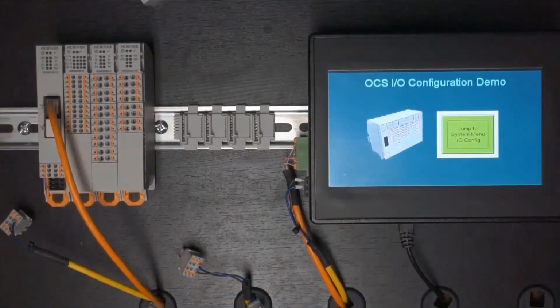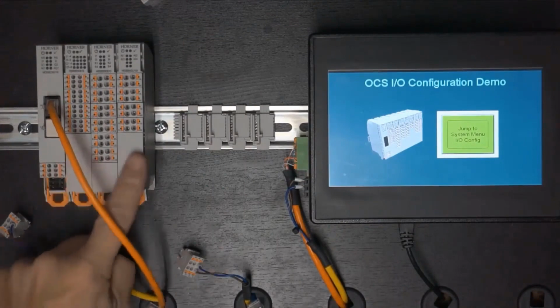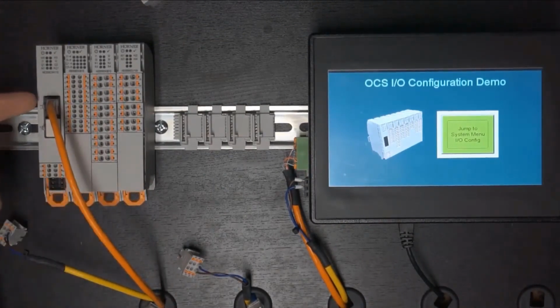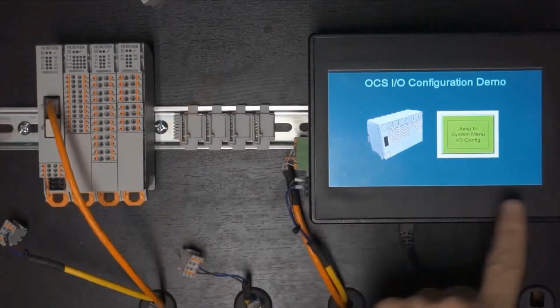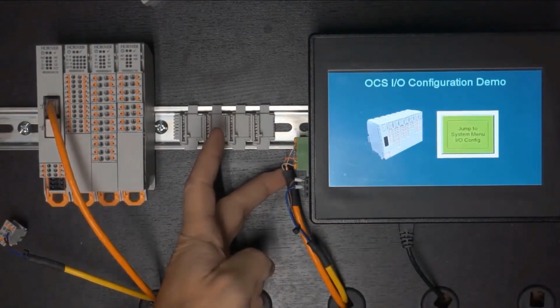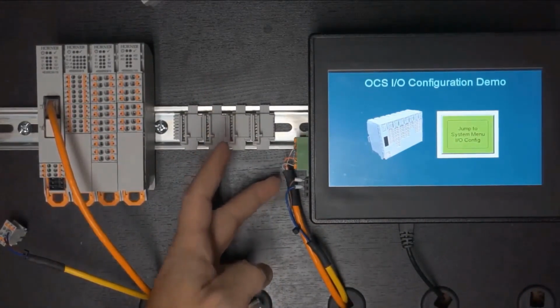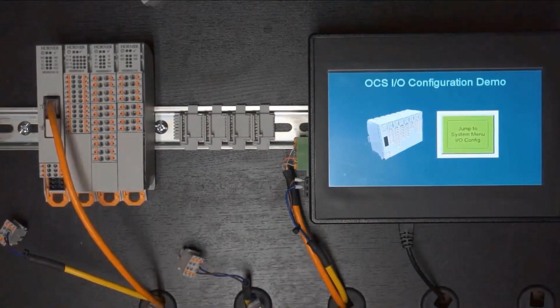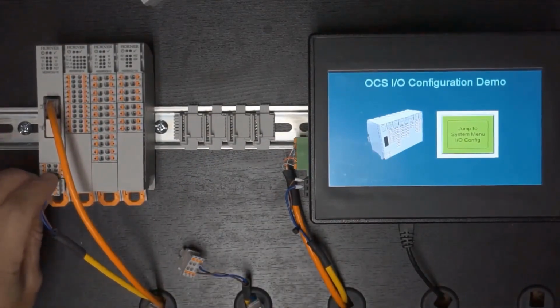Now we'll start the series of demonstrations on doing actual configurations, starting off with a single base system and then moving to multiple base systems. So here we have an OCS-I/O rack which is connected electrically to the OCS through CAN cable here, which is actually a modified patch cable. There's a terminating resistor installed on the second RJ port here on the OCS base, and the base is not powered up yet, so now we'll power it up.